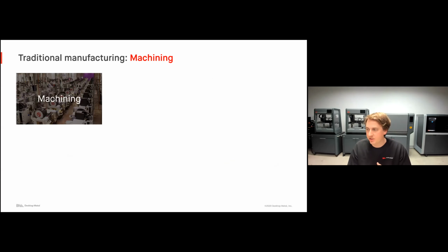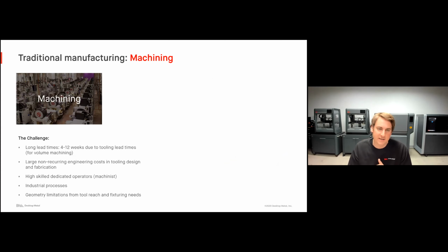Some of the other challenges we see in machining specifically are these very, very long lead times. Generally, you can see 4 to 12 weeks. Here, we're talking about volume machining. We're talking about hundreds of thousands of parts, because this is when you're generating this hard tooling, this fixturing, to ensure you can produce parts quickly and at low cost. Of course, with that tooling design, you're going to see some large non-recurring engineering (NRE) costs, both with the design of that tooling and fixturing, as well as the actual fabrication.